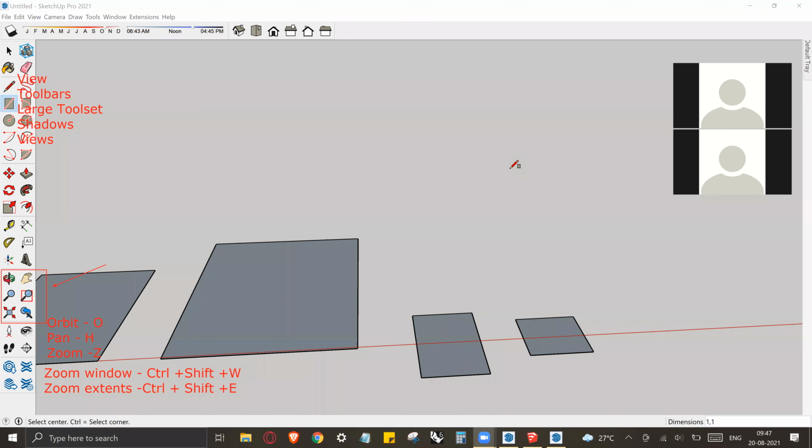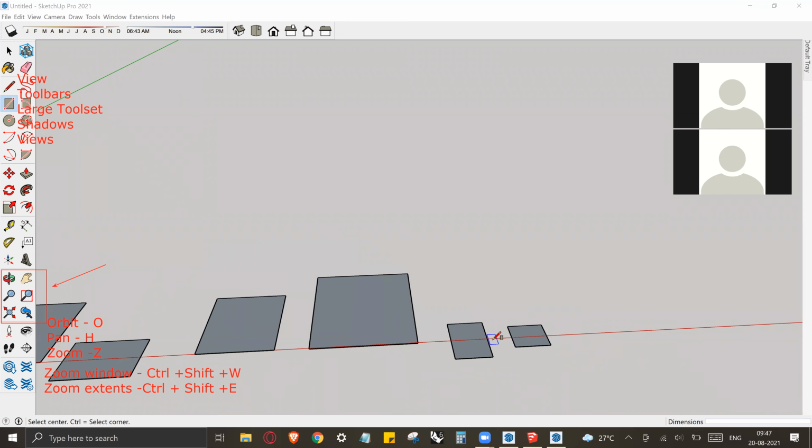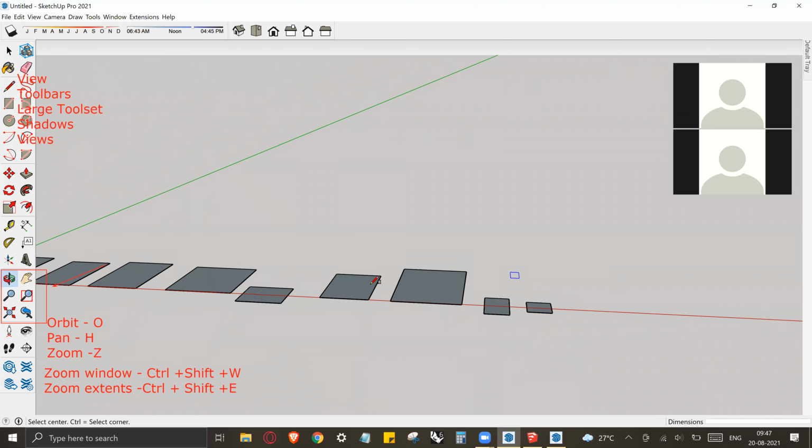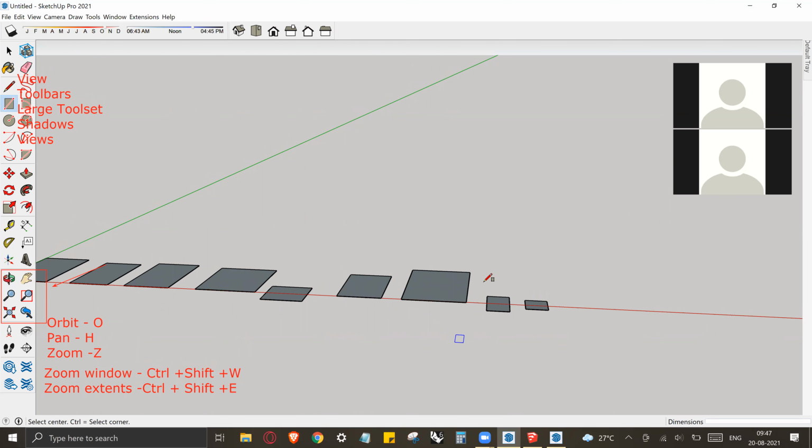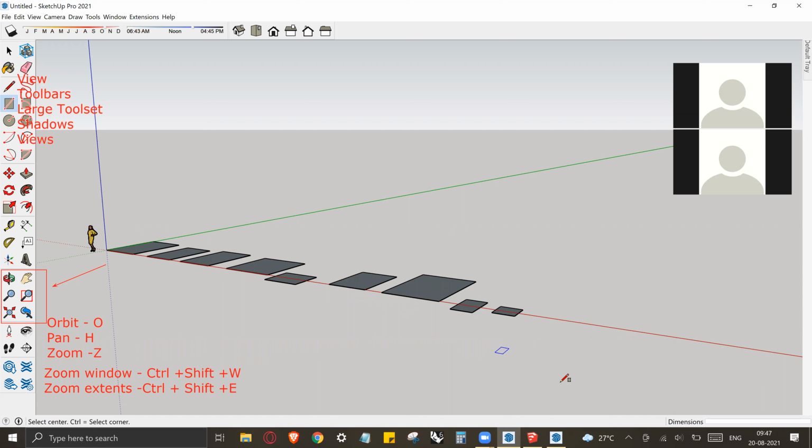So this way you can create your entire surface here. Now guys, we're just going to give it some thickness. That is your height. For this, you are basically going to do something called extruding, which basically in SketchUp means you're just pulling it or pushing it down.